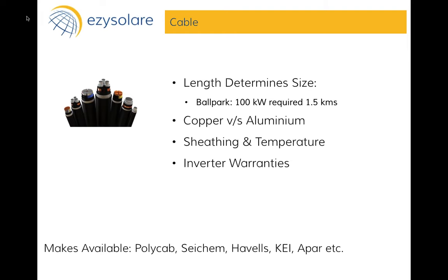The next is the number of inputs. This is fairly straightforward. The larger the number of inputs, the larger the number of module strings that you can connect to the inverter. And as a result, the fewer the number of inverters that you would need to have.